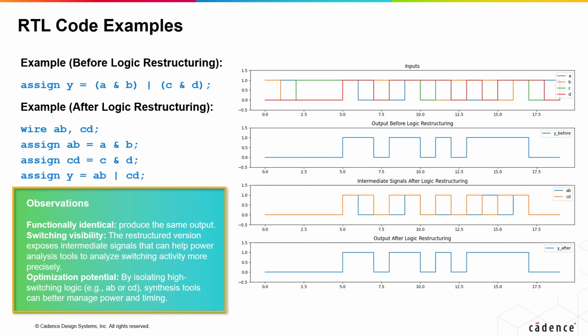However, it is necessary to understand a few points. Logic restructuring produces the same output, but the restructured design shows the intermediate data, which assists the tools for power analysis more accurately, and it also helps to split the high and low toggling logic.